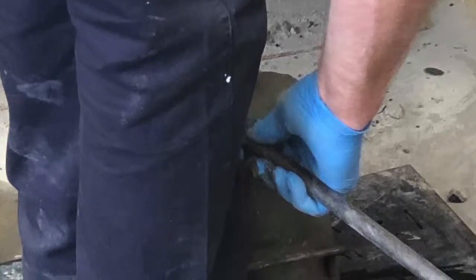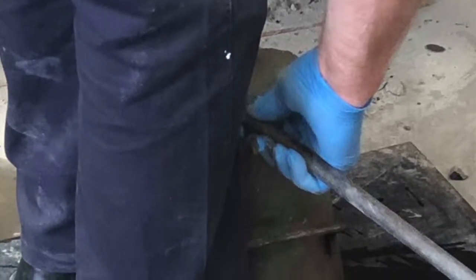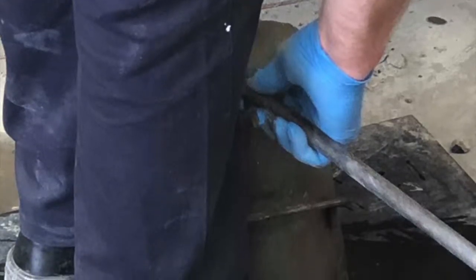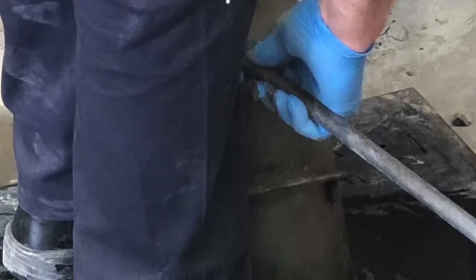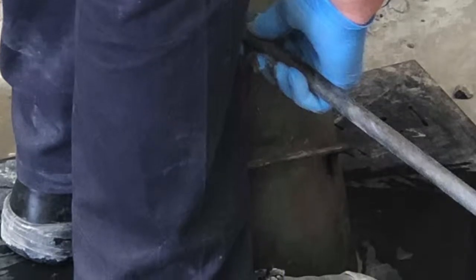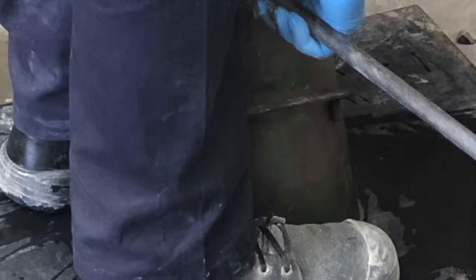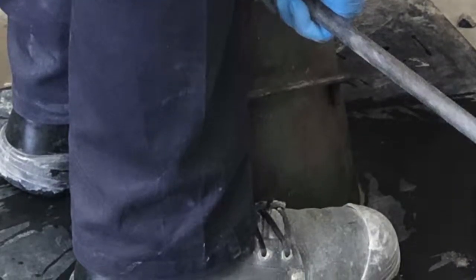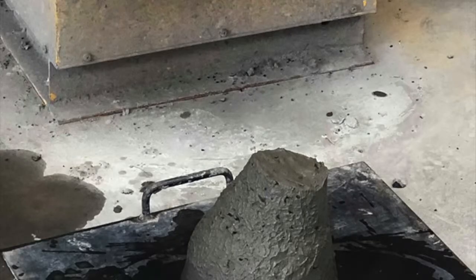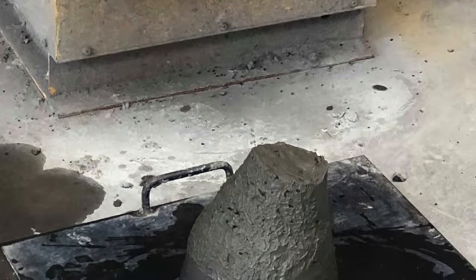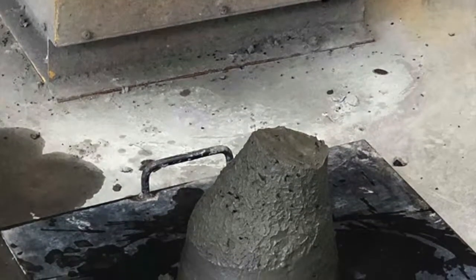A knee joint is used to connect the rafters to the columns and must be strong as they support the roof loads and must also prevent bending, and in some cases haunches are used as they reduce the depth of the rafter. The final main connection is the base connection, which consists of a single plate welded to the end of the column and attached with four holding down bolts. The bolts are fitted with anchor plates and are cast into the concrete to prevent pull-out.